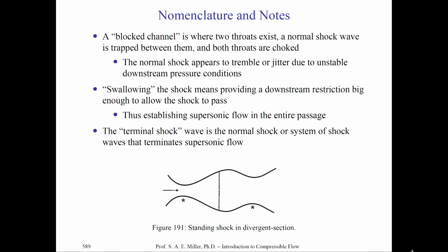The second major concept we've learned is called swallowing. This means that the shock wave is pushed downstream through a second area, which must be large enough for the shock wave to pass through and rest in the divergent part of, say, the second critical throat.